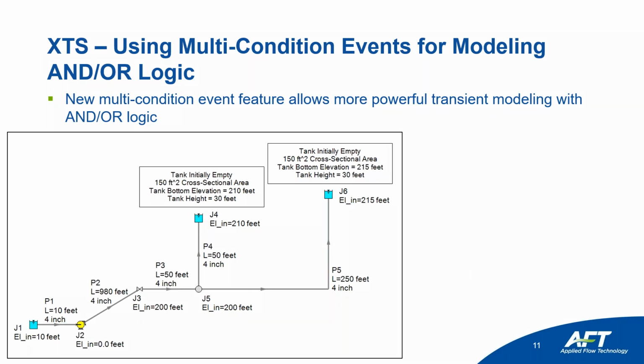All right, back to the model here. Here's the situation I'm working with. I've got a pump, and I'm delivering flow to two separate discharge tanks. Because I'm using the XTS module, I can model finite tanks with an actual geometry right here. So if I specify a tank height, it is possible that those tanks can overfill. And if you overfill, Fathom will warn you about that. And if it's a hazardous chemical, or even if it's water itself, you don't want your tanks to overfill.